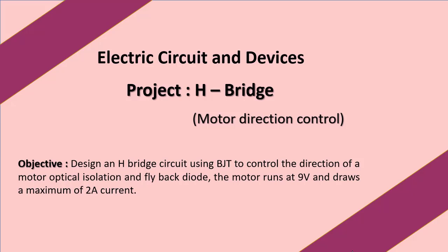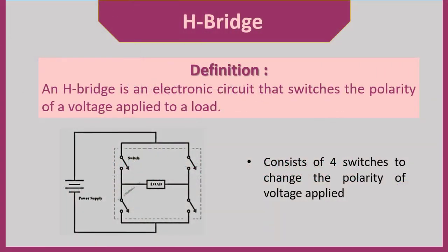Our objective was to design an H-bridge circuit having flyback diodes and optocouplers to control the direction of the motor. An H-bridge is an electronic circuit that switches the polarity of a voltage applied to the load using four switches. The switch can be a manual switch or BJT or FETs acting as a switch.